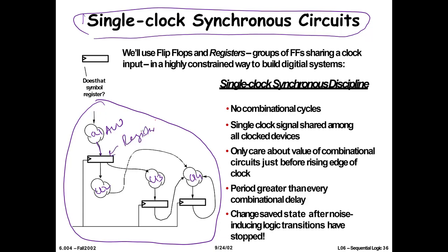This is a register or memory element, and basically register and flip-flops are the same thing. A flip-flop is a single bit register. When you have multiple bits, then you don't call it flip-flop, you call it register. So a register is a multi-bit flip-flop. So for example, this may be ALU, this may be your floating point unit, and all are connected in a way that you have some cloud where computation happens, then you have the storage, then again another computation, another storage. So the whole of your circuit can be designed in this fashion.